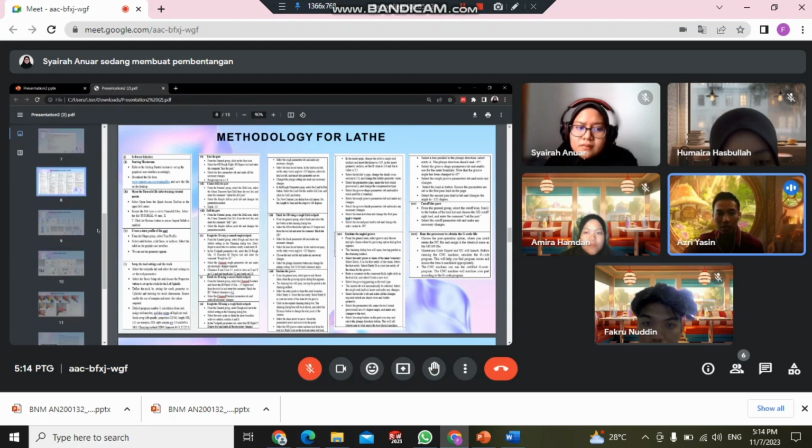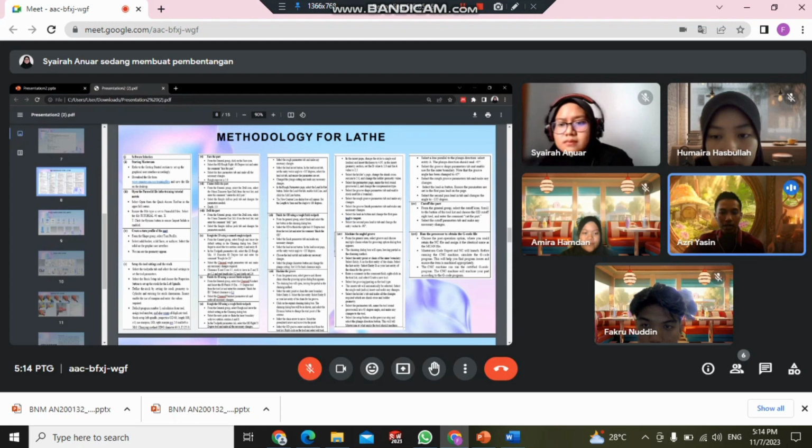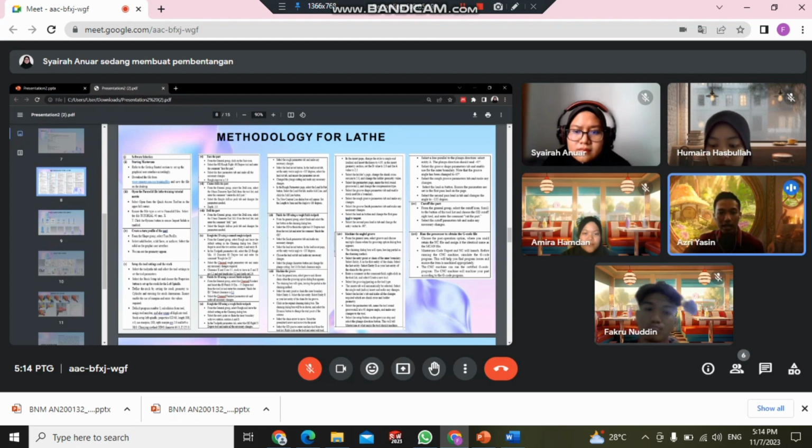We need to edit the tool, change the style to single and insert thickness and insert geometry section. In parameter, change the composition, and then in groove shape parameter, use stop for outer boundary. Okay, next, groove finish parameter, change the direction for first pass to CCW, and then in turning groove in general, choose chain and then choose the right entity for A and B. Create a new tool and choose grooving, edit tool, choose single, insert geometry and holder geometry. In parameter, we set the composition and set up the tool, choose plunge tool and click at the right entity.